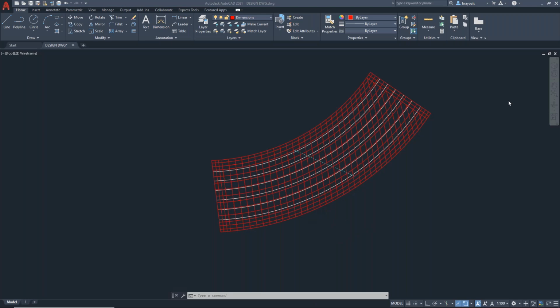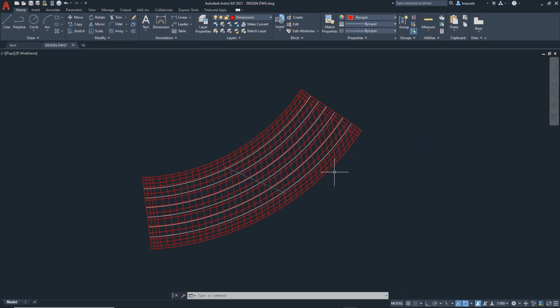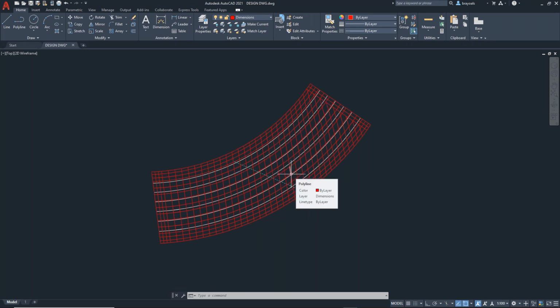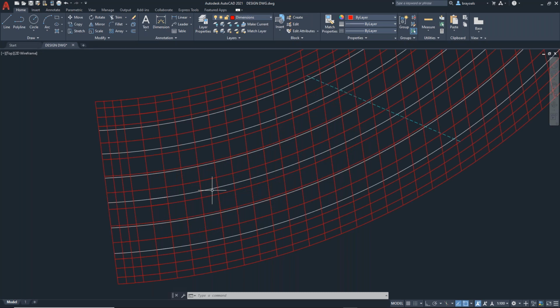This is our bridge. We drafted it in AutoCAD, and then, of course, these are some of the different elements that we used. So basically, you have to draw your grillage system or your finite element arrangement. You draw each and every element. You should take note that if you use lines, then these will become beam elements. If you use polylines, that's when they will become plate elements.